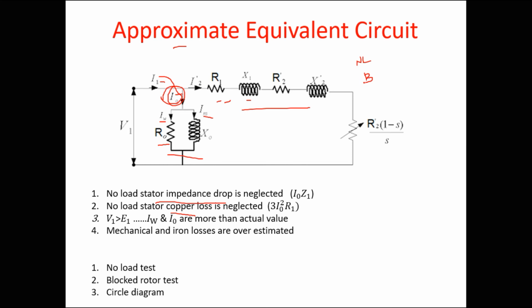So until now we have discussed the equivalent circuit of the three-phase induction motor. We have compared that with the equivalent circuit of a transformer. So from the primary of the transformer we have obtained the stator for the three-phase induction motor, and for obtaining the equivalent model of the rotor we have discussed two conditions. One is standstill and another one is running condition.